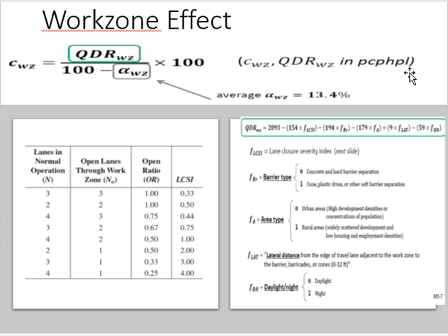The next factor I need is the barrier type. Now you're doing some construction activity, right? So you don't want the vehicles to go inside the zone, so you put some barrier. If the barrier is made up of concrete, the factor becomes 0. Otherwise, simple, 1. The other types of barriers can be steel, fiber, plastic.